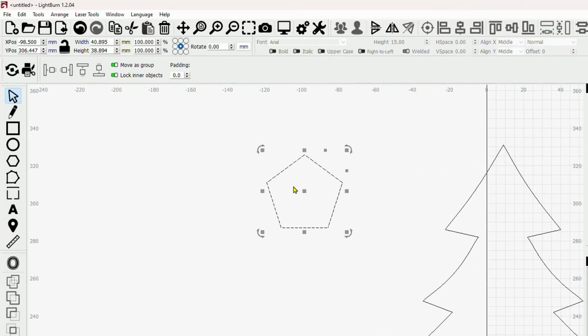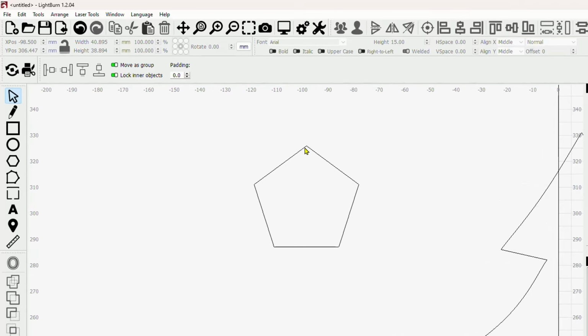And at this point, again, we're going to come back to the pencil tool, because even though it's a star, it's not really a star. So we'll grab the pencil tool one more time. When it turns into a bullseye, we can click, and we're just going to bullseye every single corner in here just by clicking around to all of the different corners like this. Every time we see the bullseye, we're going to do that. When we hit the last bullseye, it'll automatically close.